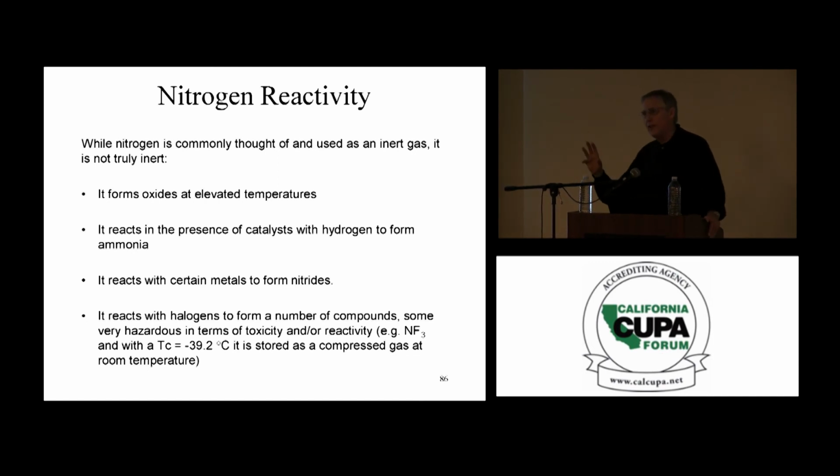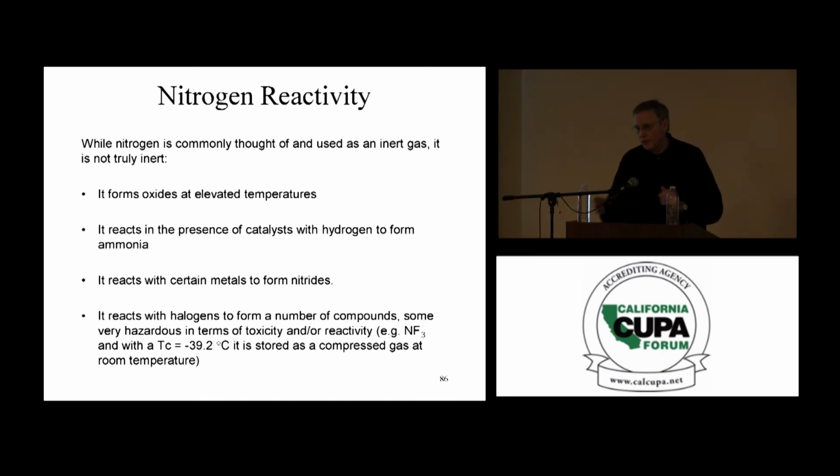Many of you will not necessarily run into a situation like is shown here, or welding with large pipes. But there are other situations with asphyxiation hazards that you have to be aware of. For example, if you have a facility where you have dewars of nitrogen, liquid nitrogen stored, that vent. They're typical.